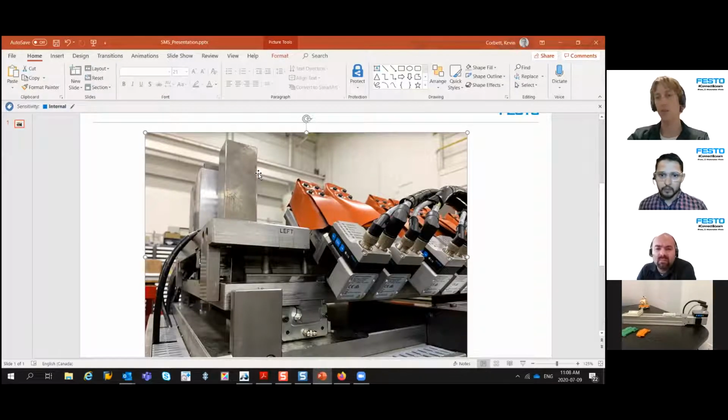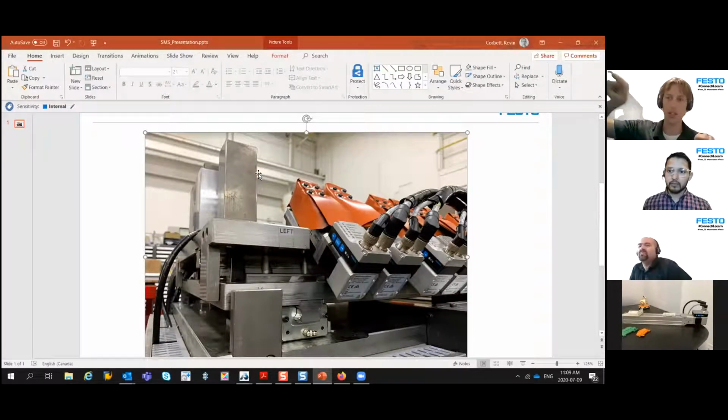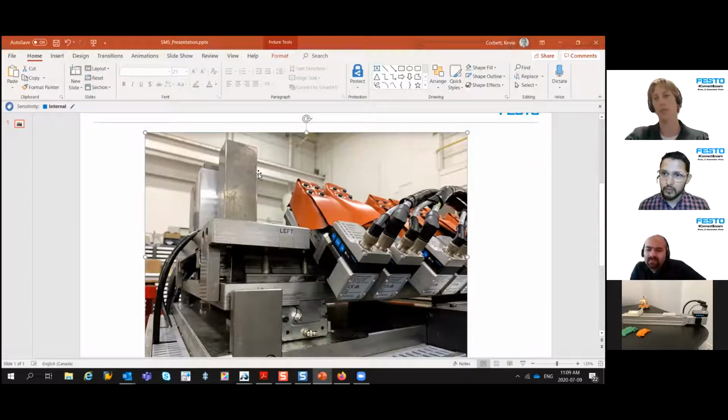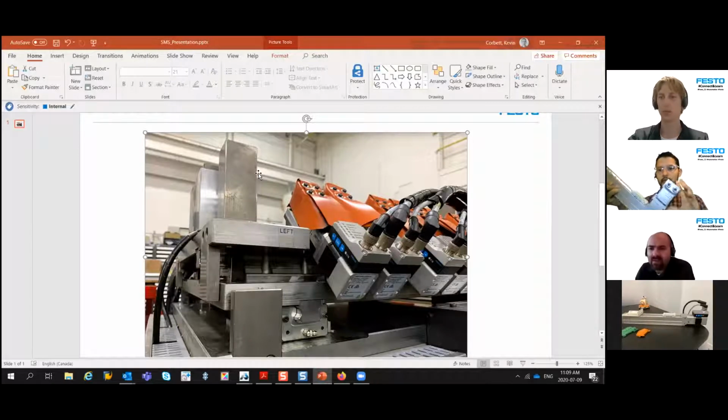Now, for position measurement, they have a built-in encoder. That encoder counts the pulses of the motor rotation, so you can actually track in a very linear fashion what position the cylinder is at. So now that linearity error is no longer an issue. Now we get a nice, constant feedback signal. The nice thing here is you don't have to have a different length of sensor. I think that's one of the challenges that I had before.